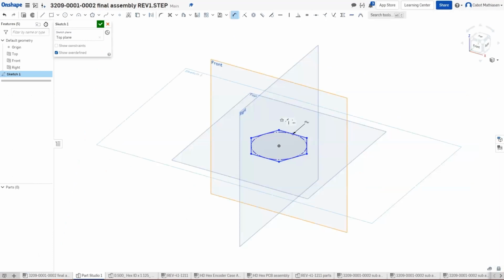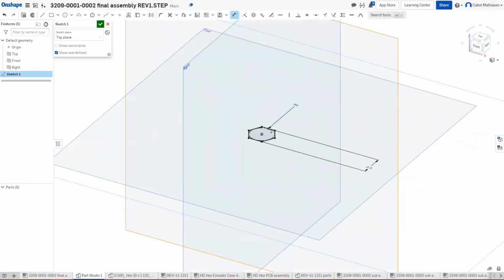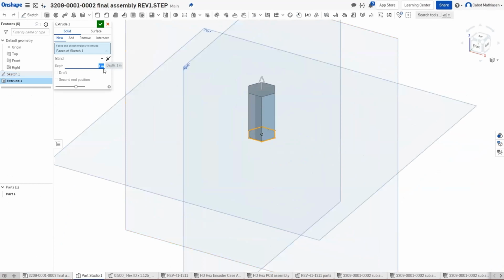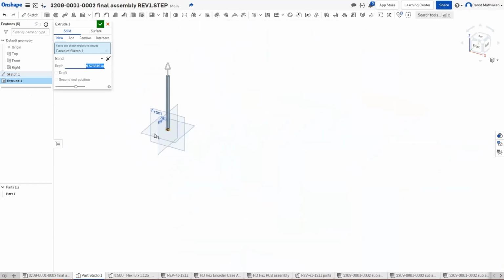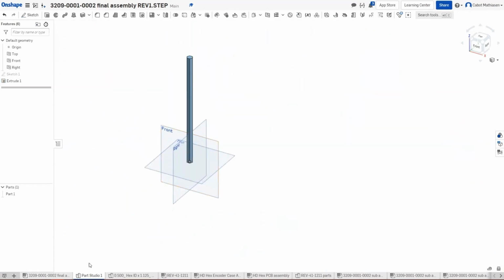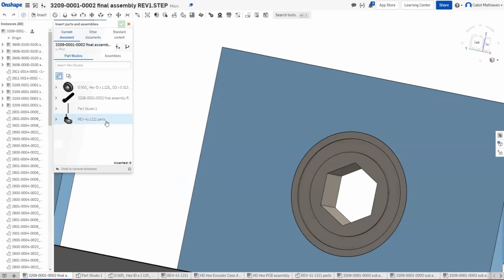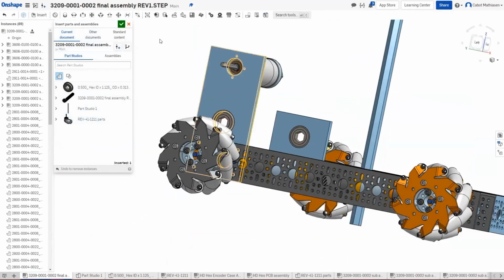So we'll just take a dimension and click on both sides. And now it is a 1/2 inch hex. So now let's do the Shift D again. We'll paste in that number, but we also want to have 3/4 of an inch on each side for clamps and sprockets. So plus 1.5. In Onshape, you have to have parentheses on each side, otherwise it doesn't realize that's an equation. So now it'll work, and we can just insert this into the assembly.